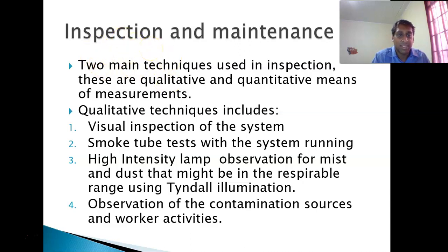They can look at the quality of the filter, if they were able to dismount it and see what contaminants are inside. Then they have an idea whether the system is working or not. For example, if you had a lot of dust in the workplace and upon careful examination of the filters you realize the filters are clean, then it's not capturing those contaminants.